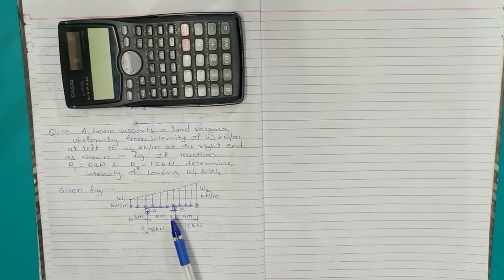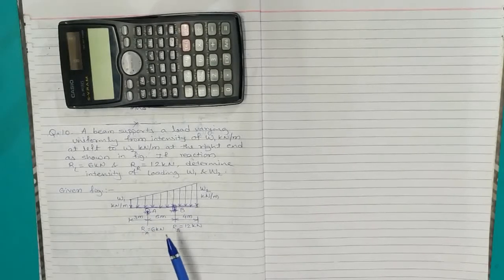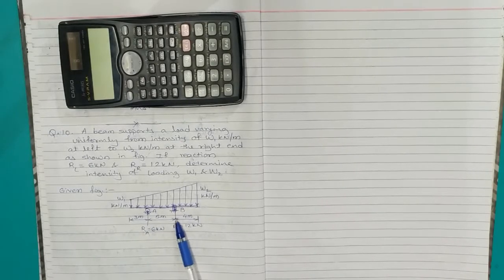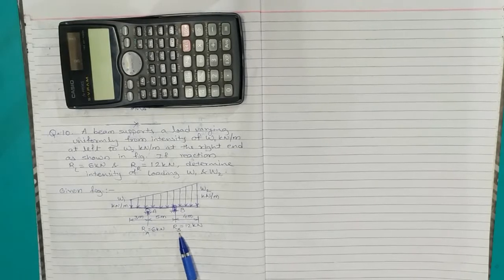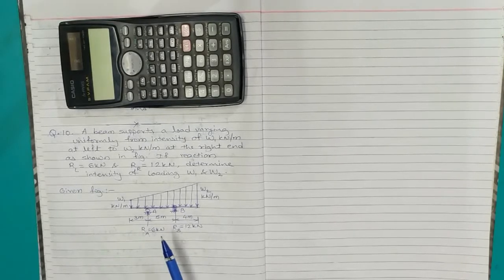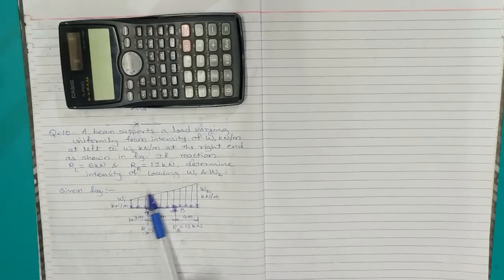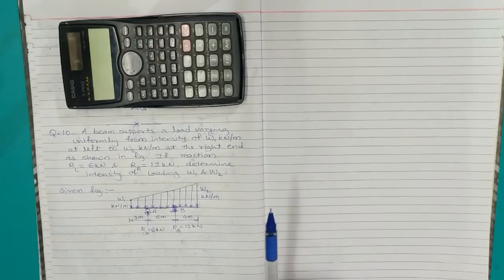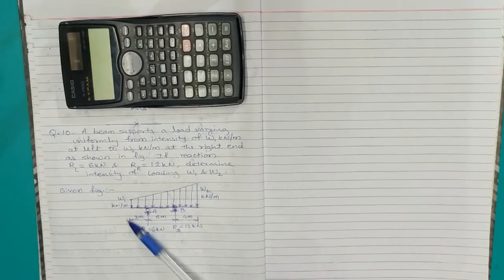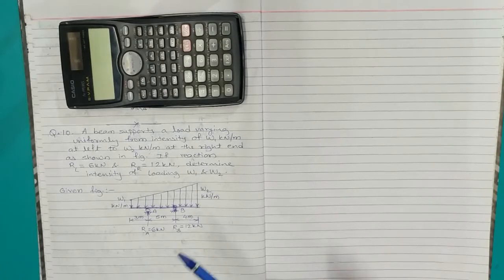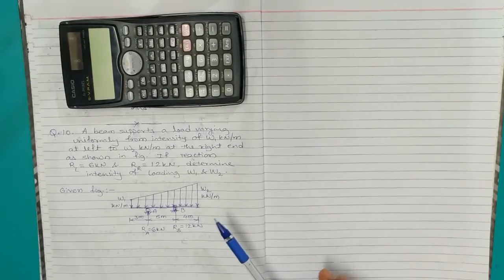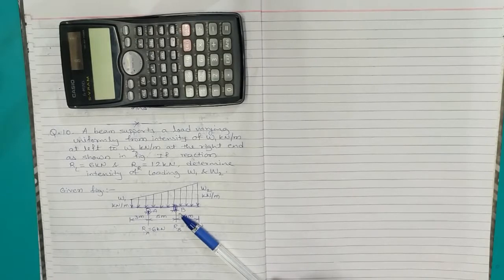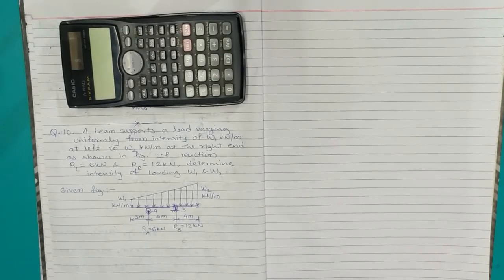We know that hinge has two reactions, horizontal and vertical, but still here we have only vertical reaction given. Now by this time you must have guessed the reason why. We have a trapezium loading which we are going to convert into two equivalent point loads which are going to be vertical in direction. So in the entire system we don't have any horizontal or inclined force. That's why the horizontal component of the hinge is going to become 0.